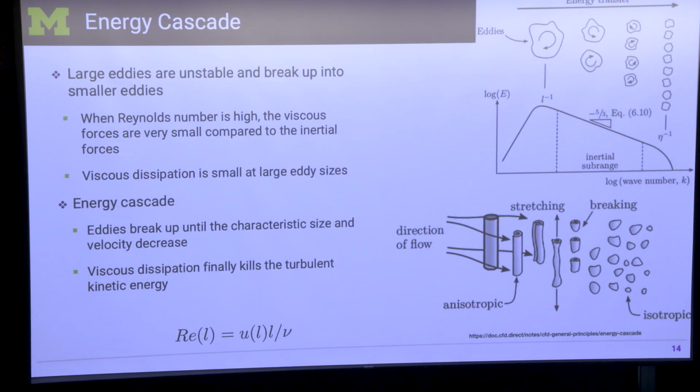There's a particular thing that happens. There's also a poem about it if you're interested: large eddies have no option statistically but to break down into smaller eddies. So a big eddy of the size of the Florida coast cannot stay that way unless it's on the planet Jupiter. It will always break down into smaller pieces, right? Of course, there can be forces that maintain that large eddy for a very long time, and then it will stay there for a long time. But within that process, it will still try to break down into smaller eddies.